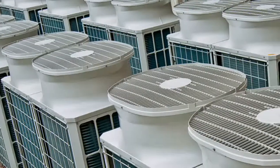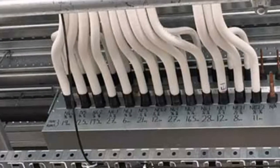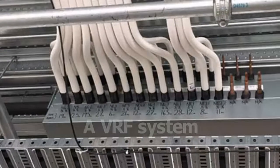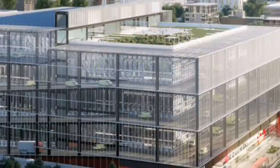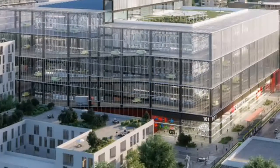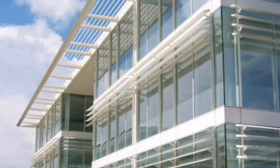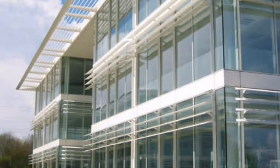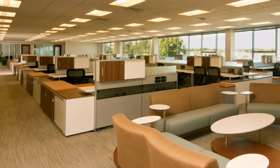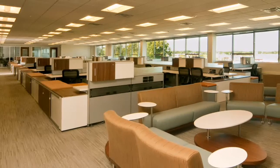An extremely expensive system called the City Multi moves heat around inside of a building, allowing every room to be at a different temperature, and it simultaneously heats and cools. These units are only found in commercial buildings or in the most expensive luxury homes. Literally, if the south-facing rooms are getting warm while the north-facing rooms are getting cold, the City Multi moves the heat from the south to the north in order to maintain the desired temperature at any point in time or during any season of the year.